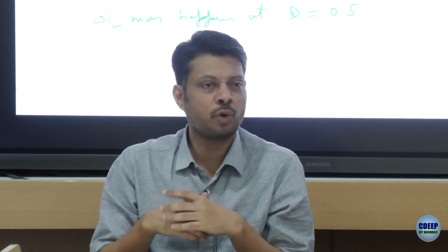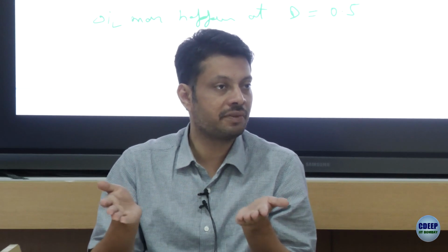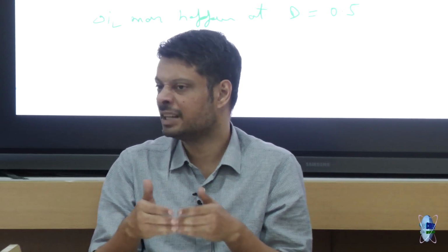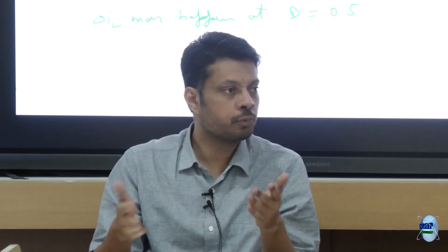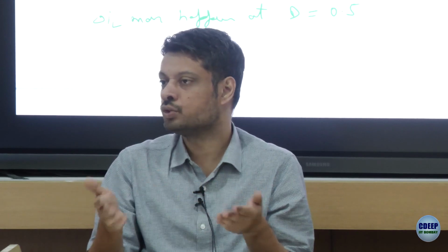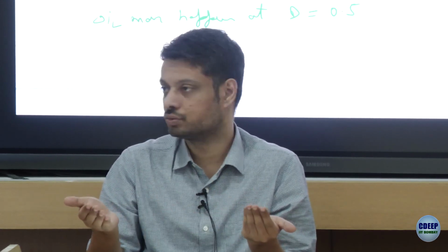Usually you won't be able to adjust duty cycle, because your input is, let's say, 48, your output is 12. So your duty is already fixed. So although yes, it's good to see what the trend with duty cycle is, it may not directly help you if the input and output voltages are fixed. D is already fixed. What you can choose is switching frequency and inductance. These are the only two things you can choose.